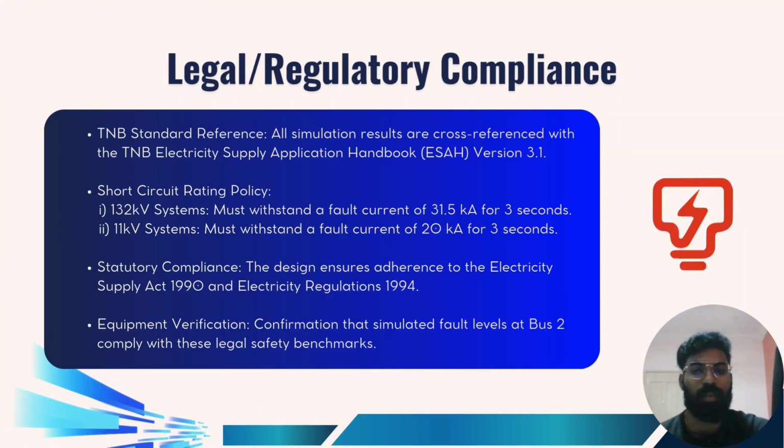And the next one is statutory compliance. Beyond technical manuals, our design adheres strictly to the Electricity Supply Act 1990 and Electricity Regulation 1994. These are the legal pillars for electrical safety in Malaysia. And lastly, by verifying this fault level, we can confidently state that our simulated system isn't just theoretically correct, it is legally compliant and safe for deployment.